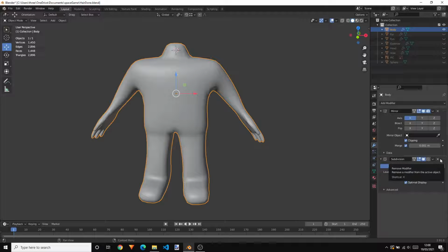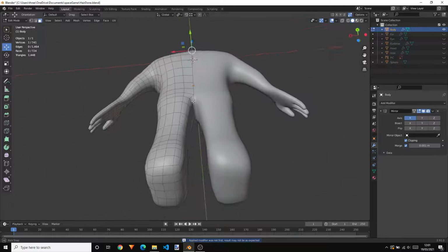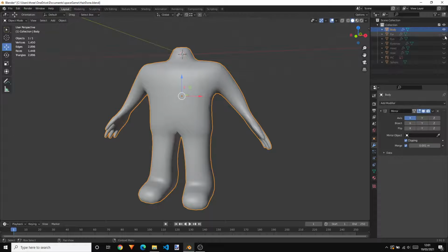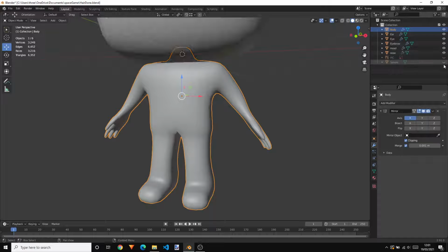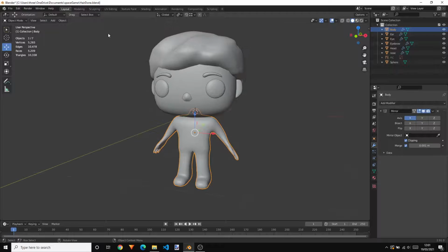If you need to do some major tweaks to the body shape, now before you apply it is a good time, but I'm just going to apply it. So subdivision and apply. You've got to be in object mode, remember to do that. So apply. So now we can see the actual real topology that's been generated, and we can now tweak that, and that's the actual mesh. So let's bring everything back. We don't need the screen, even though the background is only one face. And now, as you can see, we're down to 5,200 faces.